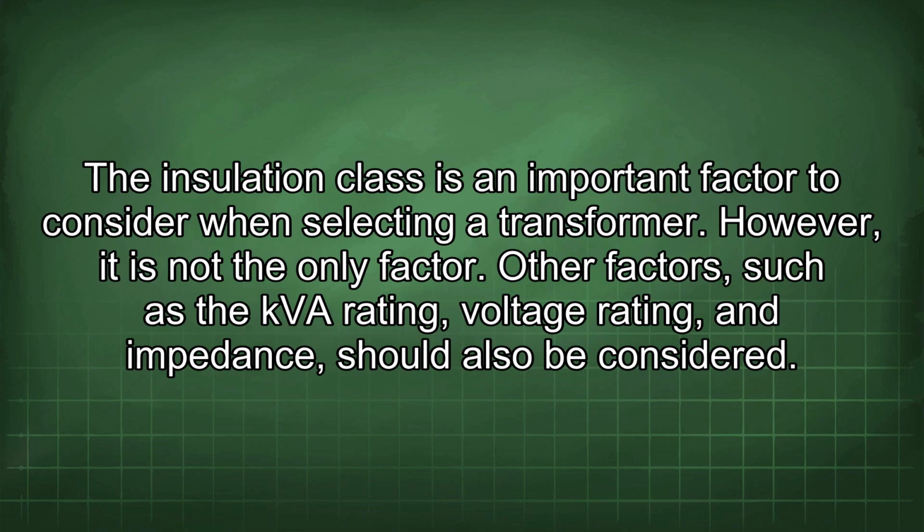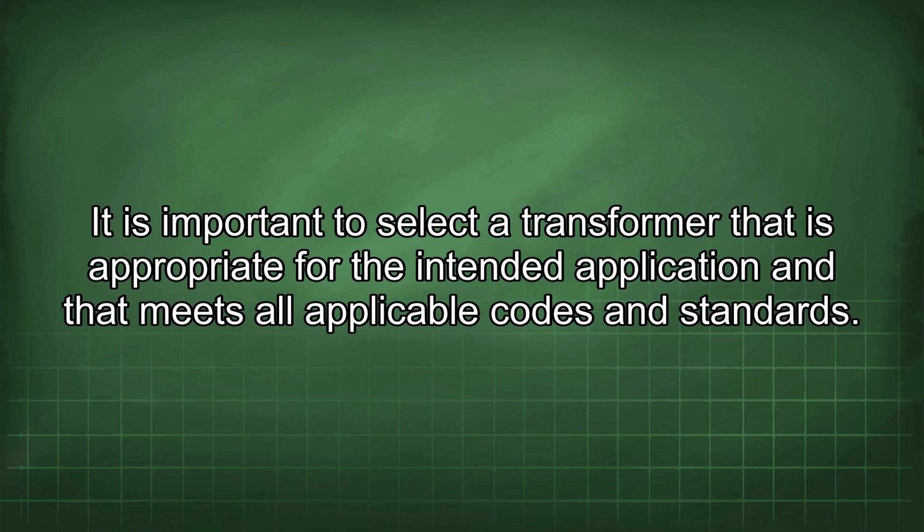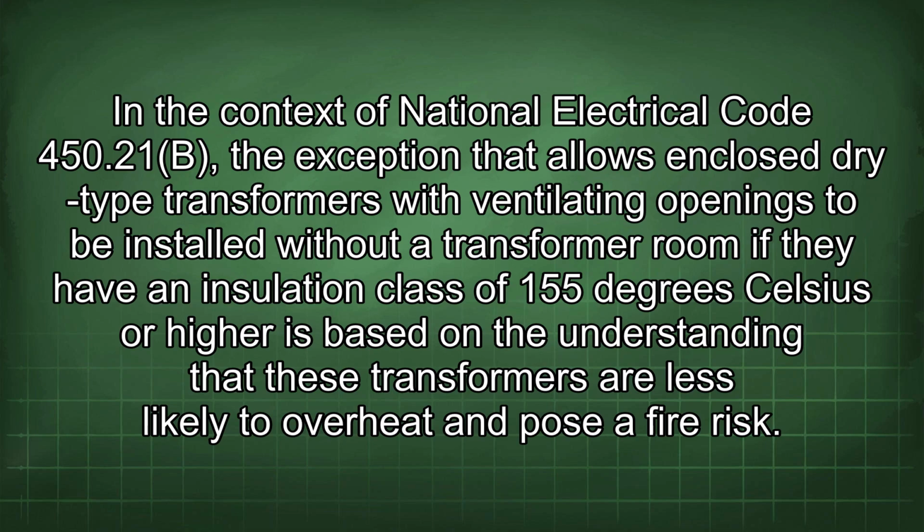The insulation class is an important factor to consider when selecting a transformer. However, it is not the only factor. Other factors, such as the kVA rating, voltage rating, and impedance, should also be considered. It is important to select a transformer that is appropriate for the intended application and that meets all applicable codes and standards.